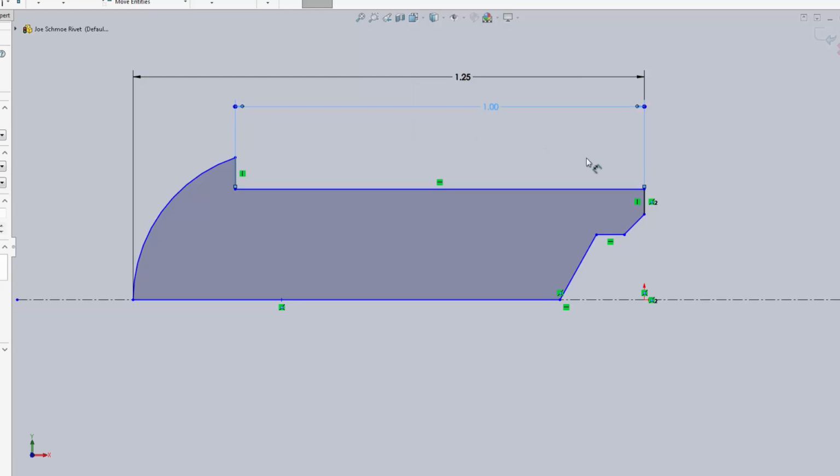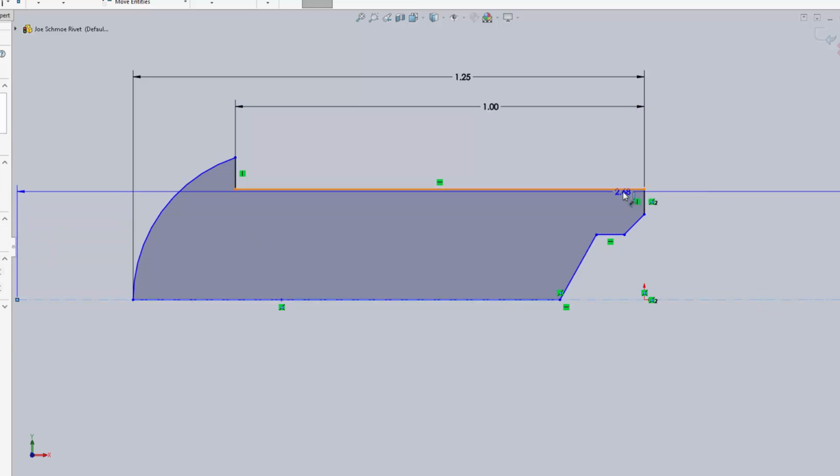Now, I want to show you a very important way of making diameters. Someone might say, well, hey, if I only do half of this revolve thing, I only get to do radiuses from here to here. But you would expect someone to want to have a diameter across this. Well, never fear, that is totally possible, and in fact encouraged. If I go from the center line to this line, I will have a radius of 0.27.